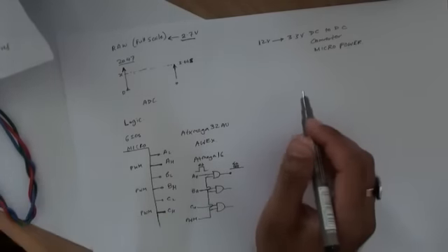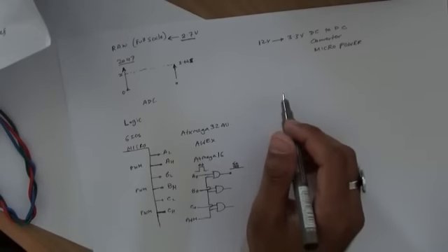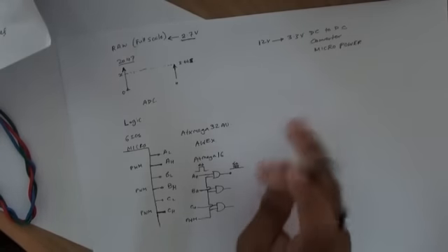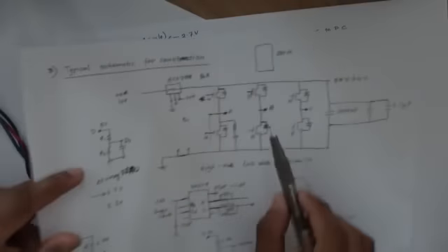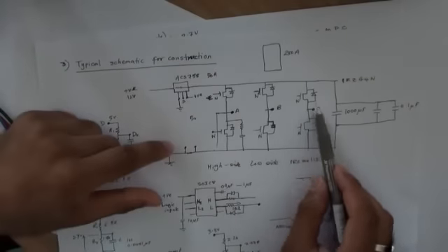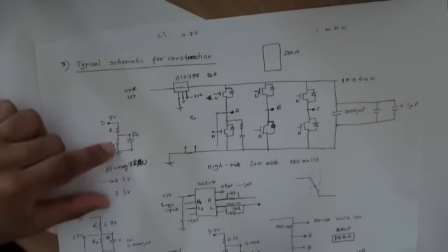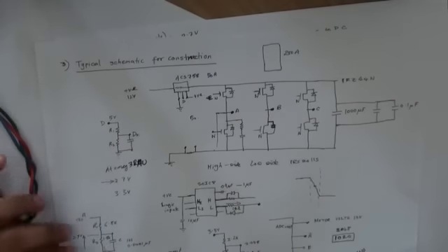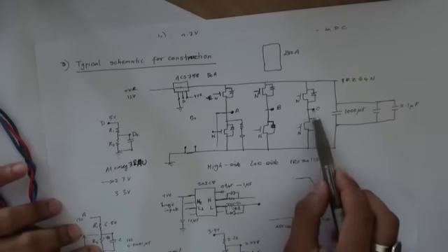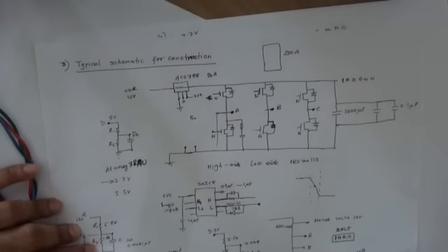Don't forget, of course, the diode clamps. They're very important, and I've learned it the hard way. I've had a situation where one of the phases came off the motor, and that back EMF was so high that it actually destroyed, even though I had the voltage divider network and then passing it on to the ADC, the ADC input for the microcontroller. The voltage must have been really high, and this happened.